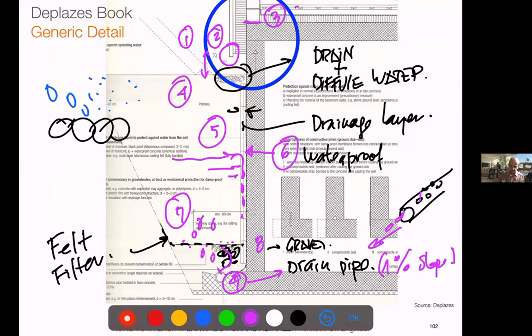So you have to think that this element needs some kind of height margin, so you can go down until you have the exit. So we have 9 elements, which are the basics of most basements. Then you can have variations. This can be brick, concrete, mortar wall. You may have the insulation outside, inside. This can be, again, timber, as we saw before. Things can change, but all those things are what we have.